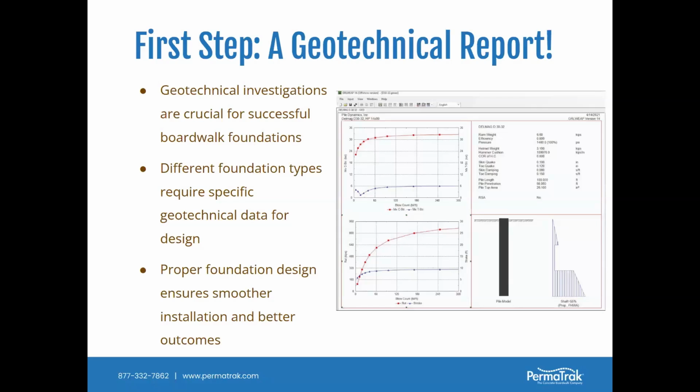A geotechnical report is going to require that a geotechnical engineer and his team go out to the job site, potentially do hand augers, potentially do some soil borings, extend down into the soil layers to some described depth, and then analyze the soil. And the soil will be analyzed and quantified, and then from that, a foundation recommendation will be made. And as you'll see from some of the future pictures, you want to match up the loading of what you're designing with the soil.